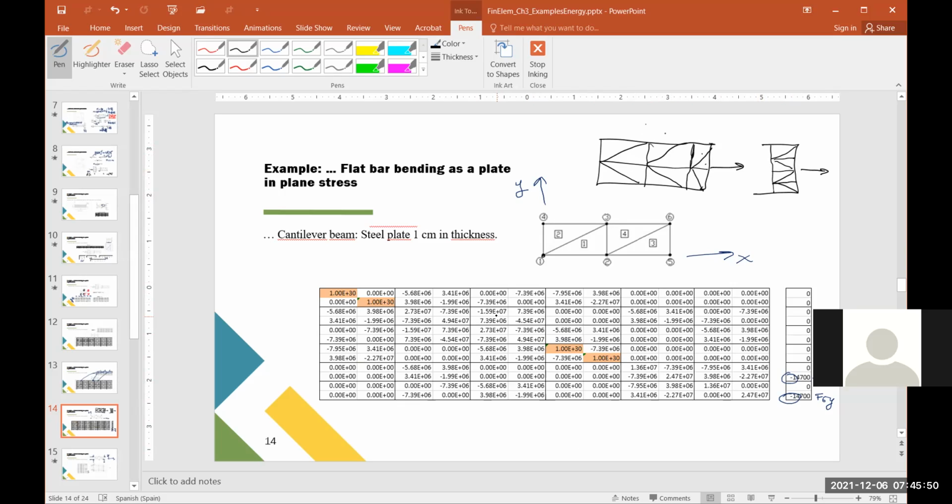How long does it take for you, Isaac, so far? How many minutes? When I use the element size of 5 millimeters, it's around half an hour. Half an hour. Can you imagine? You put the run, and you have to wait 30 minutes in order to get an answer. That's because the elements are so small that you have a very large global stiffness matrix. And you have to solve it, and he does iterations. So in every iteration, that's what he has to solve.